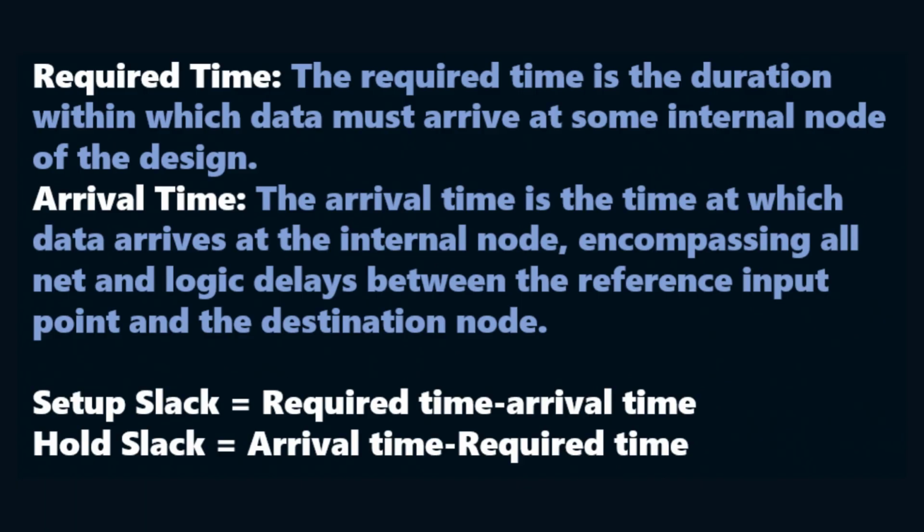Arrived early. Good. Yep. And for hold slack, it's arrival time minus required time. You also want this to be positive. Positive means the data stayed stable longer than required after the clock edge. Stayed stable longer. Also good.